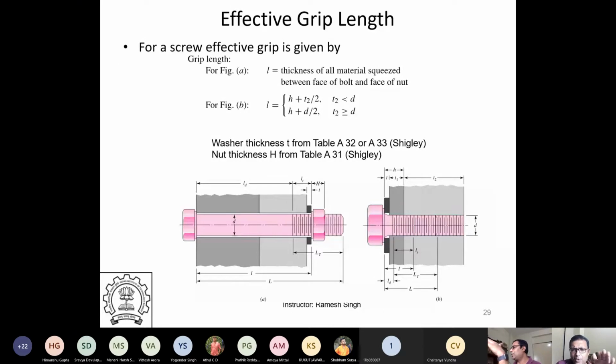So that's one aspect, that you want to understand what kind of deflections would be there. Other than that, this will also affect the structural dynamics. If we have lower compliances, we need to understand what compliances would be there, because these systems will be subject to cyclic loadings, so they can also vibrate. So we also need to estimate what kind of stiffness this system has. That is one way to estimate what kind of stiffnesses will be there here.